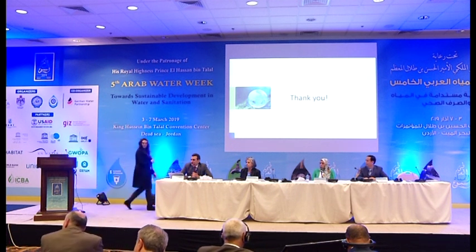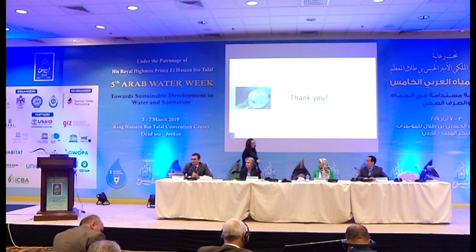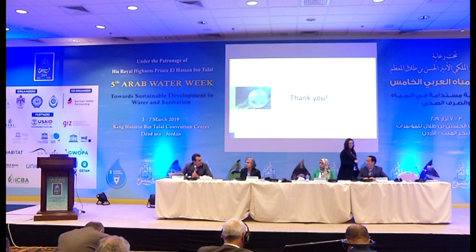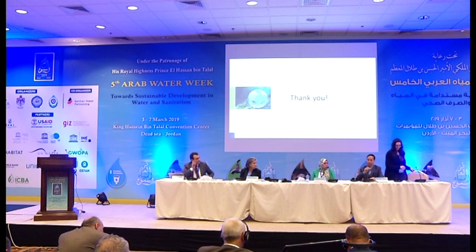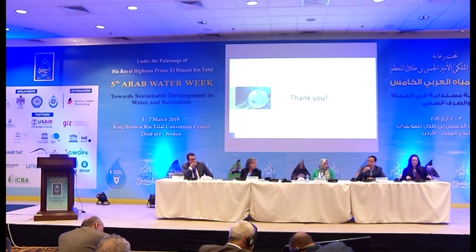Do you think that this model could be used to estimate the risk of cross-contamination within the network for specific nodes? Actually, the hydraulic models now can also model water quality, for example your cross-contamination. So we can use tracing. So let's say you have a point source, point contamination. You will see how far it reaches, how soon it reaches, how much it reaches.